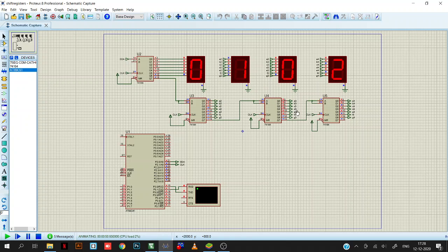The output of the shift registers is being fed to the input of the 7 segment display. For every data entered, there will be a clock pulse. With every clock pulse, the data will be entered inside, and then after the shifting process, the numbers will be displayed on the 7-segment display. So this is my power. External power will be given to the MR, that is master reset.